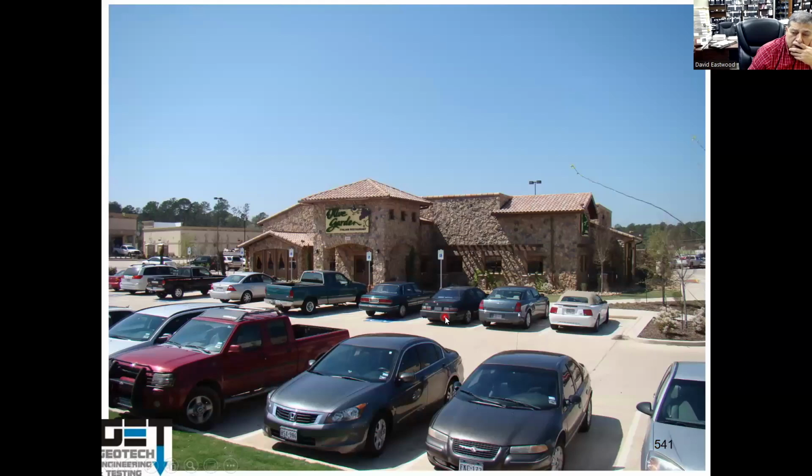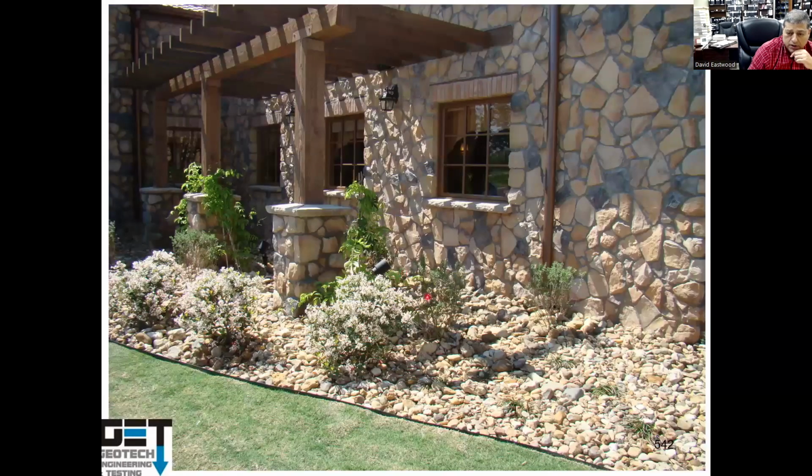Olive Garden restaurant. This is Olive Garden restaurant in Conroe. They just built it. I went out there to have lunch in it. Really a nice building, just built. Went out there, looked at it, looked at the landscaping. You see the bed liners, you got gravel. Really bad drainage condition. If it drains, water just sits here and the bed liner would hold it in place.